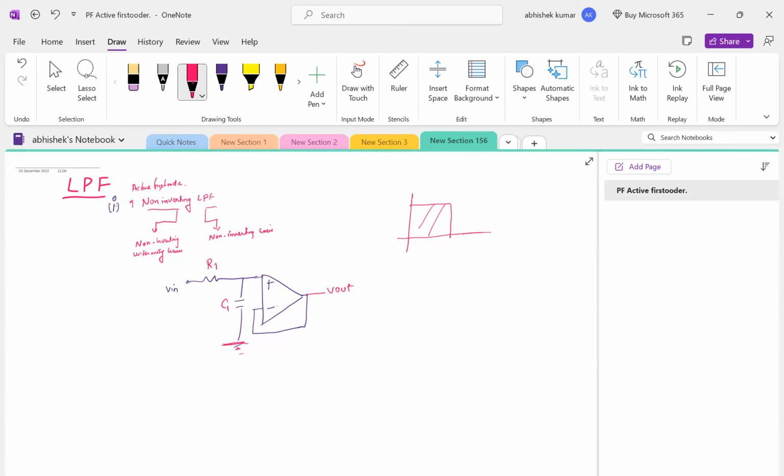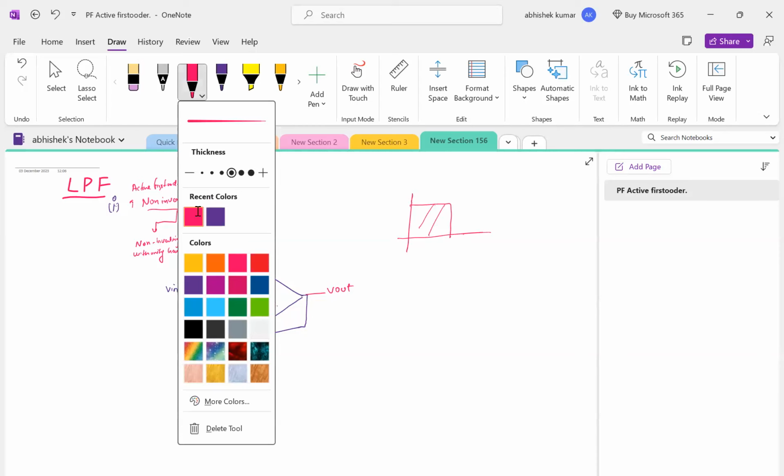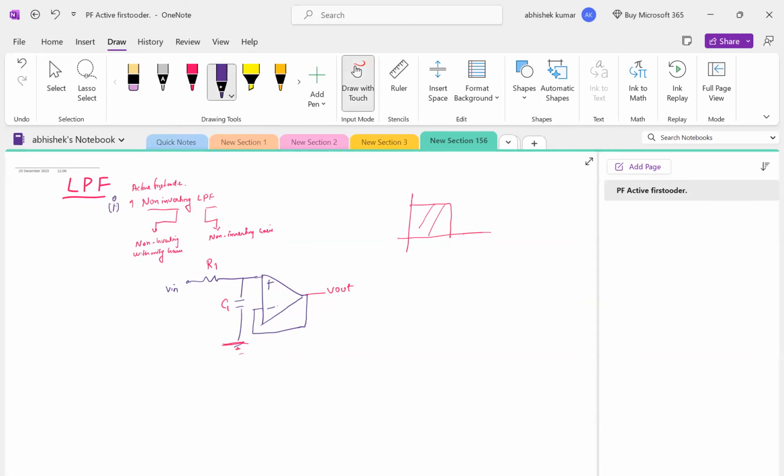It will filter AC to a little bit of DC with the ripple thing, right? Basically, I want to say, what is the reactance of the capacitor? Can you tell me? 1 by 2 pi f C, right? 1 by j omega C, right? If your frequency is high, your reactance value is very low, right or wrong?